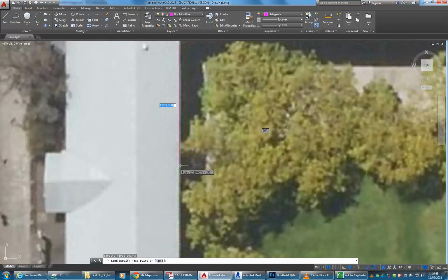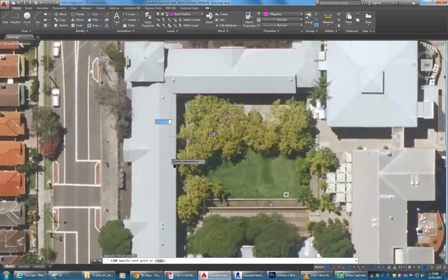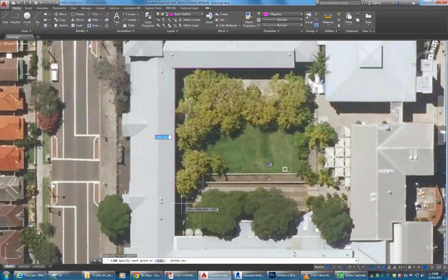Again, bring it down. You can see there it's snapping to the angles, but that's kind of a fluke because I've got polar on. That's fine, but if you remember ortho, it's another useful option which will make sure the lines are at right angles. So I'll turn that on. And then I'm just going to bring this down.